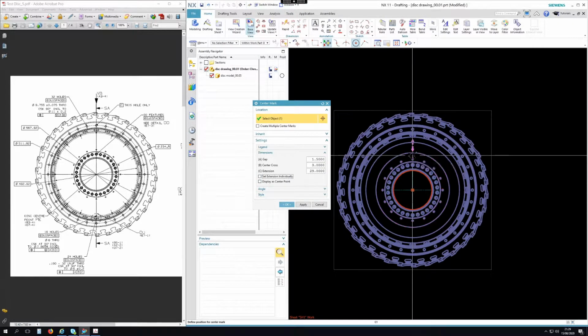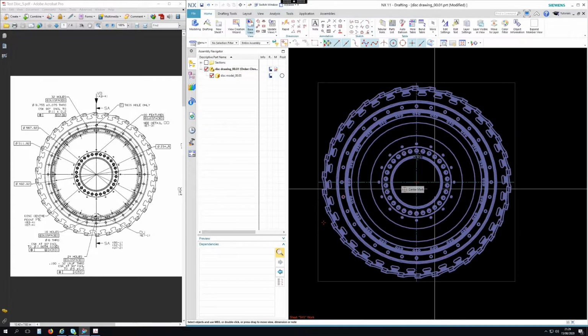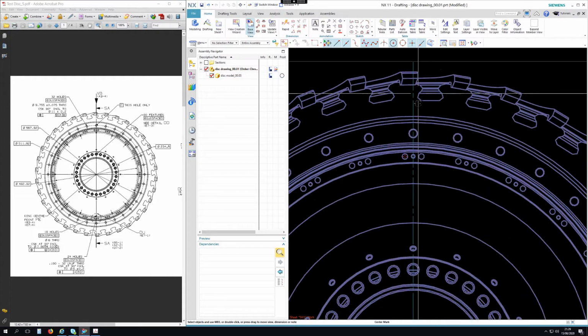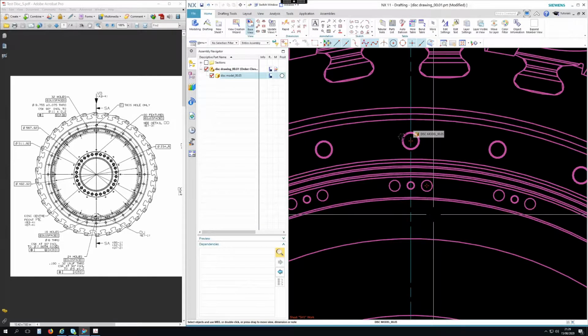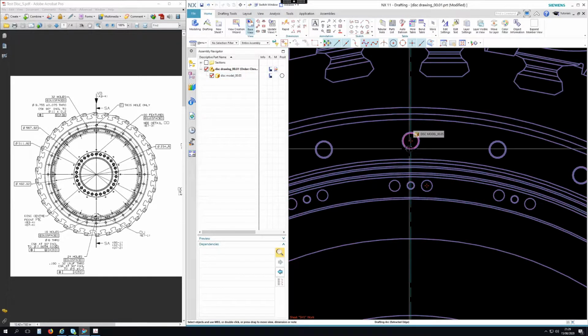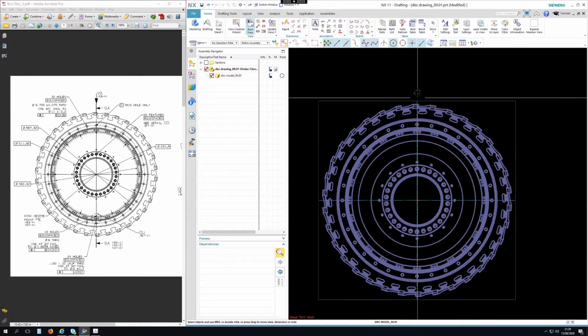I want to extend them all the same amount. So that's the first point I'm putting on, and any other center lines that go through, say this hole and this hole, I don't necessarily want to put on this line, otherwise you'll have a line on top of line, and when you go to print it, it'll probably come out a bit darker where you've got a line on top of line. So you're always best not to have line on top of line.